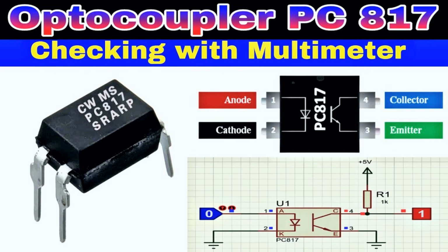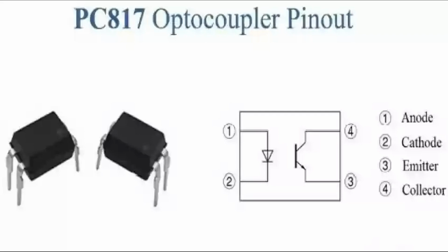Averaging techniques. Moving average. A moving average calculates the average of a set of consecutive samples, effectively smoothing out noise that varies rapidly. Exponential moving average. This technique gives more weight to recent samples, allowing it to respond to noise changes more quickly while reducing the impact of old noise.